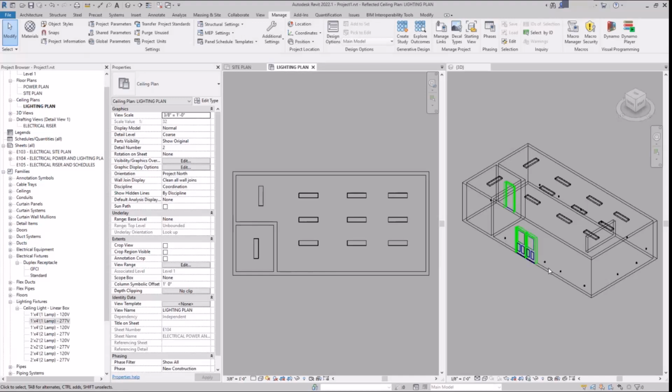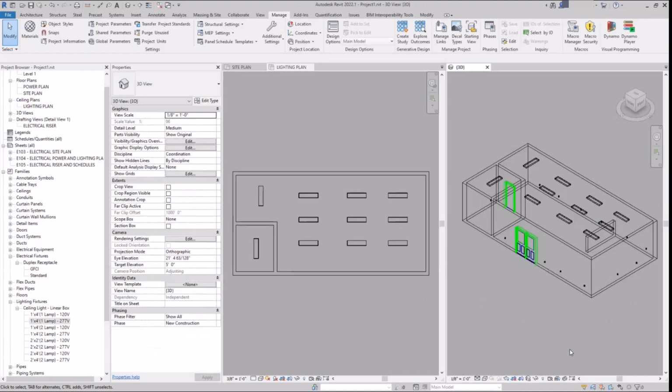Obviously, we did that very quickly. Most of the time, it's going to take a couple of hours, if not a couple of days, to verify you've got all the equipment in there. So as you're going through, look at the mechanical sheets, look at the plumbing sheets. You want to make sure that you've got an outdoor unit powered. You want to make sure that you've got the hot water heater powered if it needs it, or if it's gas, or if it needs a receptacle and it's gas, and so forth. Look at mechanical and plumbing at the same time you're doing your electrical sheets to make sure that you're all matched up. Right?